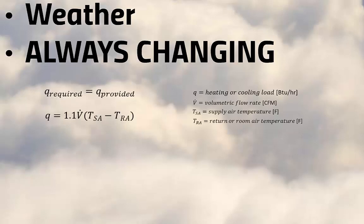How much heating or cooling the air system provides can be determined by this simplified equation. I say simplified because this equation truly is an estimation. We encourage you to take some AFIT HVAC design and analysis courses if you want to dive deeper into this equation. In this equation, Q is the heating or cooling requirements of the space in BTUs per hour. V dot is just the volumetric flow rate in cubic feet per minute of the air entering the space. It is also the flow rate of the air leaving the space. Remember, those two flow rates need to be equal, otherwise the building's pressure will build and build until it literally explodes.